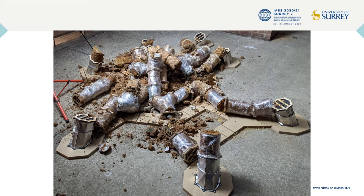We learned a lot about the spatial structures with mycelium-based composites. Although the overall framework works well and the structure worked in compression-only manner, some minor deficiencies, like the mold issue caused by the wood and the lack of proper drying protocols, caused an early collapse.